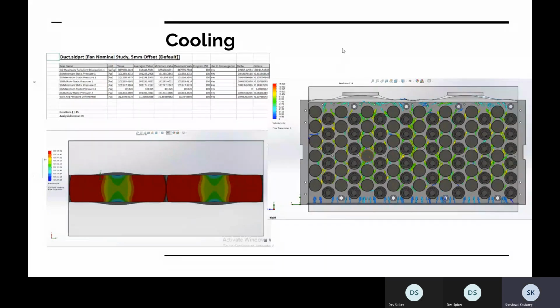So, the design of this cooling duct was pretty non-trivial, I'd say. I iterated on a couple of things, those being the curvature of the surface sweep you see there, as well as the width and diameter of the openings.